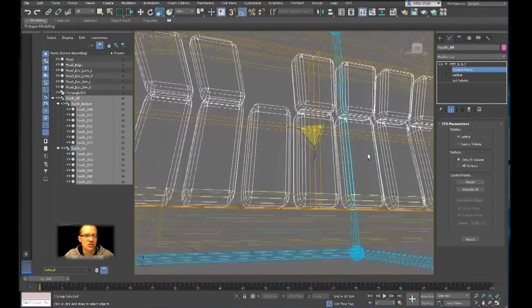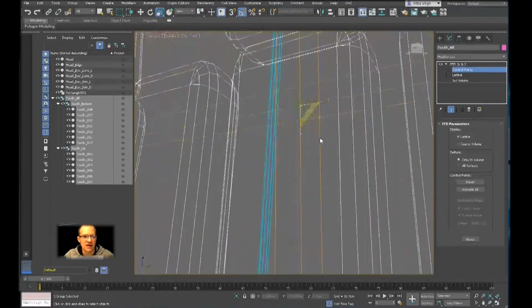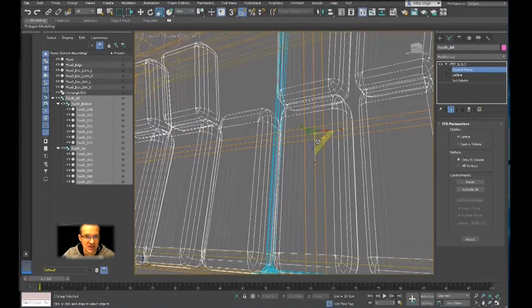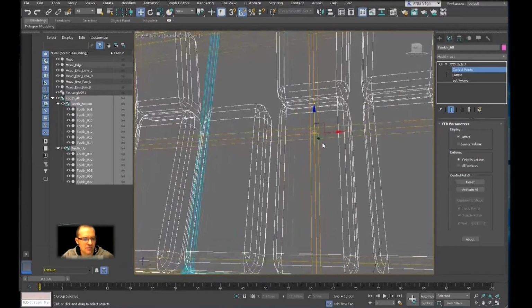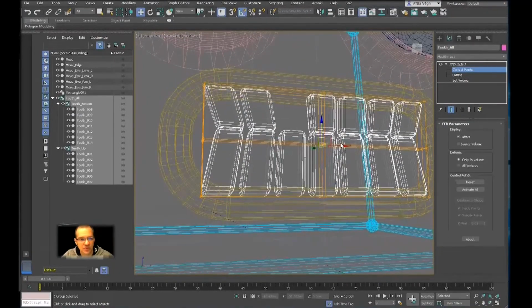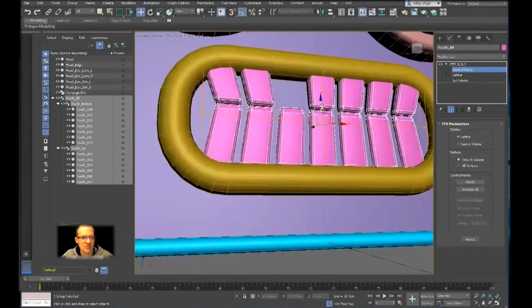If you're not sure, you can slightly rotate around and check the colors. If the color shows that it is yellow, that means that particular point is selected. And now I'm switching to move mode. On the top here, you can select the move cursor, or right click and move, or W. And this is what happens if I start to move this along the Z-axis.